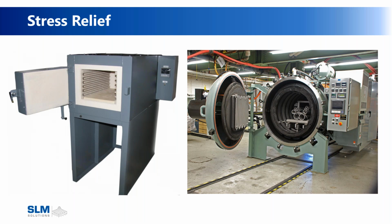But if you're going to do stress relief and even heat treat, including things like titanium, which has a high potential of picking up oxygen, a vacuum furnace like we see on the right may be an investment that's needed, or at least find a provider for vacuum furnace heat treating to be able to heat treat these parts and, one, achieve mechanical properties, but also two, relieve stress and prevent warpage of the parts coming off of the plate.